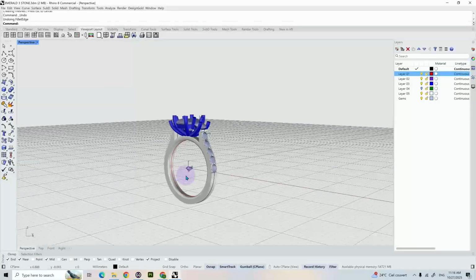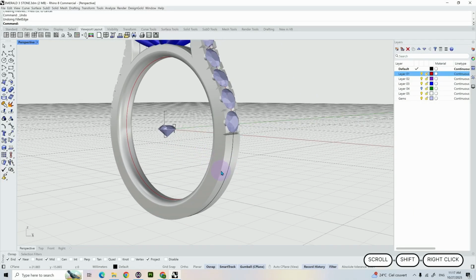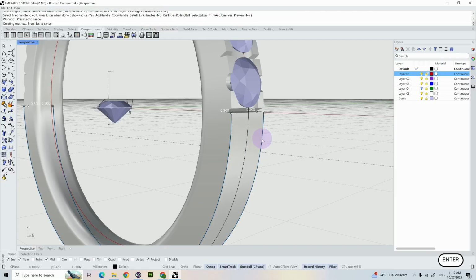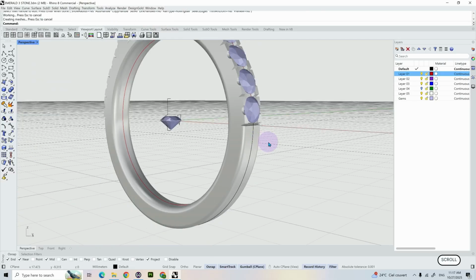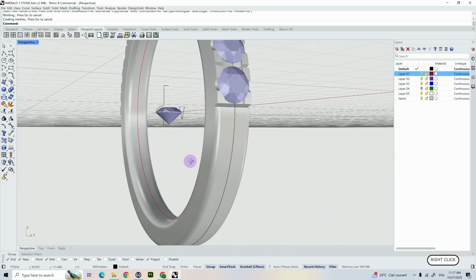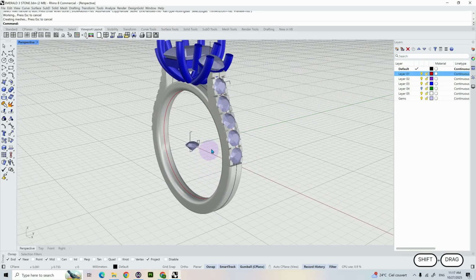And guys, of course, you can refine your shank, especially the outside of your shank, by running a fillet edge command. And for the radius of it, simply make it at 0.3, select both sides and run your fillet edge, and ta-da! Rounding off those corners is important, not for production but for rendering, which is something that I will cover in a future video.